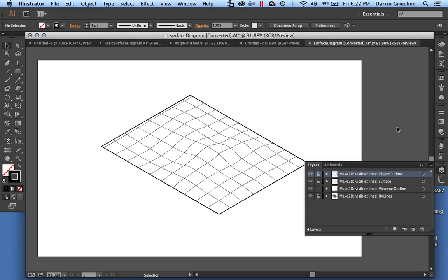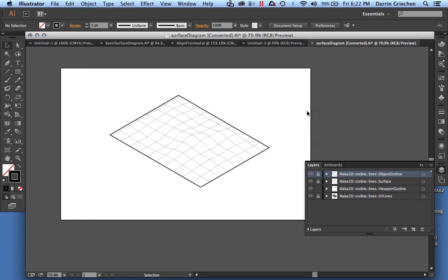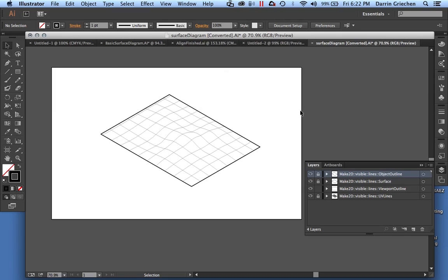and unlock and unhide our border background, because that's going to help us bring in the rendered image. So the next thing we do is we want to place the rendered image behind there. So the two things we need to do is that we need to create a layer for that rendered item to come in on. So we go down to the bottom of the Layers tab, click New Layer, and then we're going to call that Render. And then we want to make sure that that's highlighted so that that's our current. So that's where it will place the image.